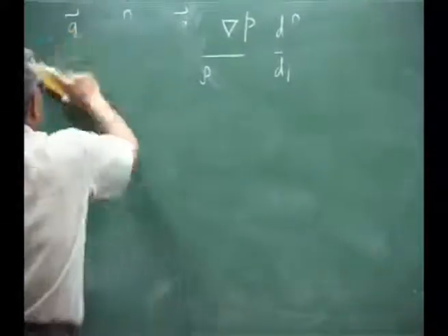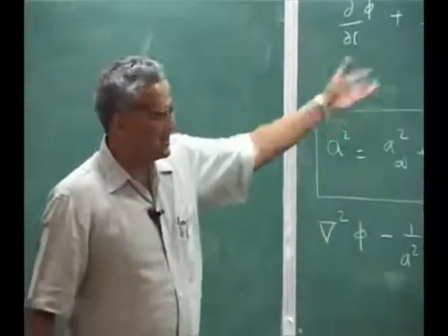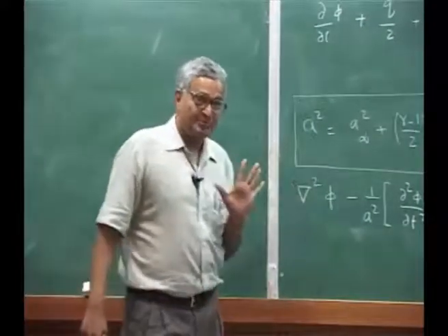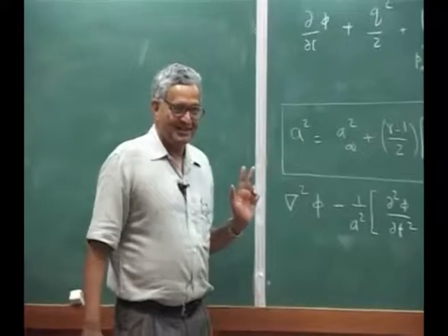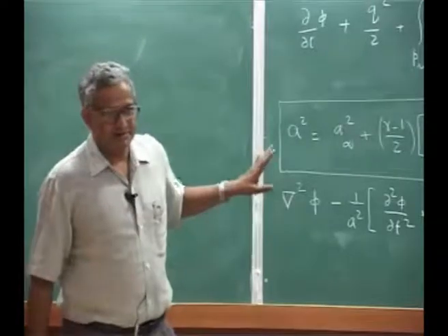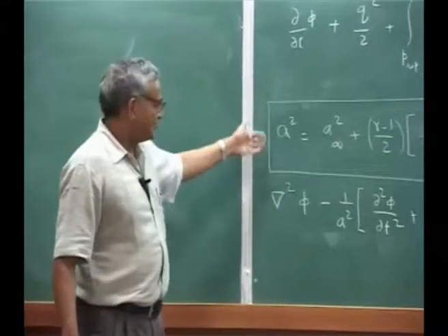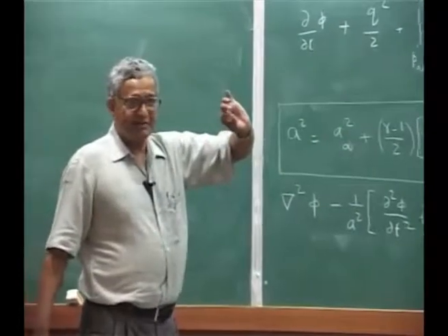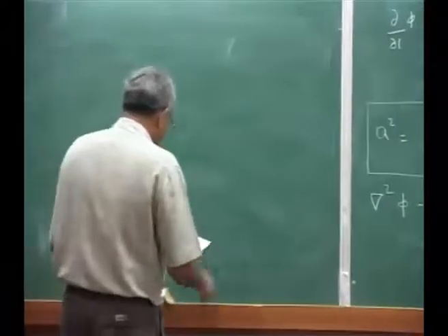But this is all algebra. Finally, please understand one thing, the algebra is, that is why you get lost in so many differentiation, substitution, back and forth, etc. But that has nothing to do. Finally, you need to get these two equations, that is all. And the whole idea is continuity equation, momentum equation, and we have invoked inviscid, isentropic, irrotational flow. And they brought down to this equation. That's all. And this is valid for any speed, even 0 to Mach 0.3, because so long as you don't have intense heating, isentropic relation is still valid. That's all. Okay. Now let us take the boundary condition.